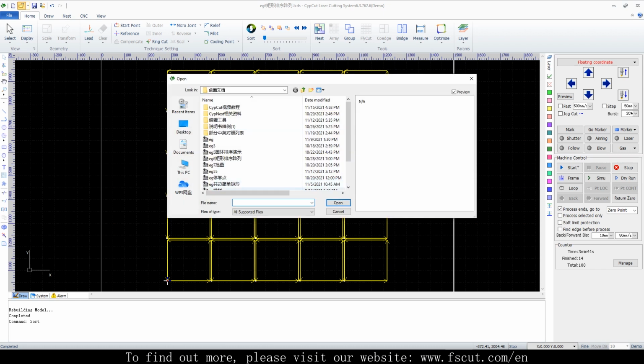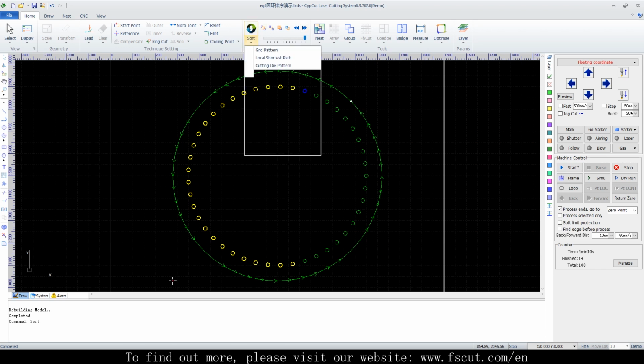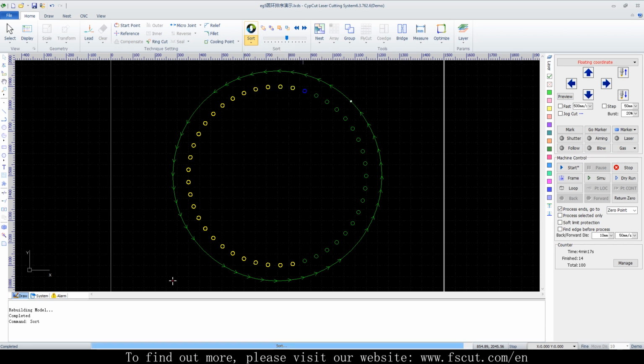When we cut this kind of graphics, as we can tell, if we use these four modes for annulus, this is inefficient. But radiating outward, clockwise and counterclockwise are just perfect for annulus patterns. This way can we skip over unnecessary travel paths and hence improve efficiency.